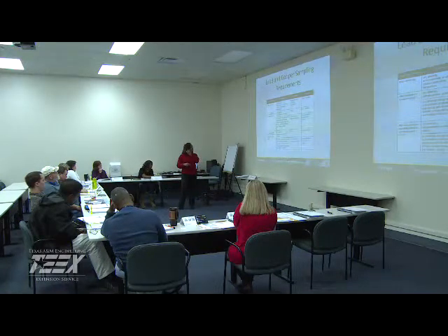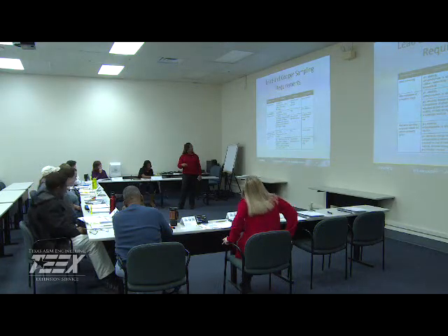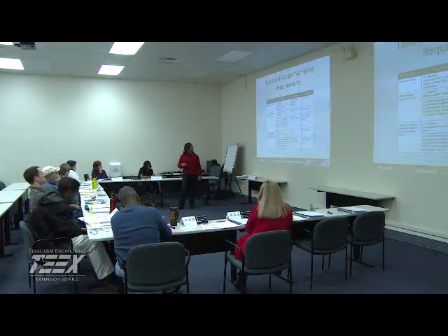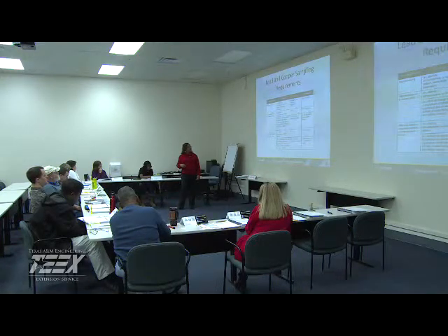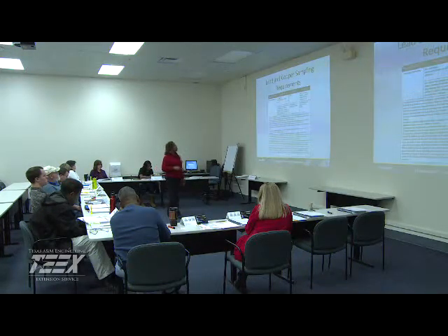If and when the state specifies parameter values for optimum control, corrosion control, again, same frequency here every 6 months, dose rate and all of that of your inhibitors no less frequently than 2 weeks. And a lot of systems will probably do it a little more often.